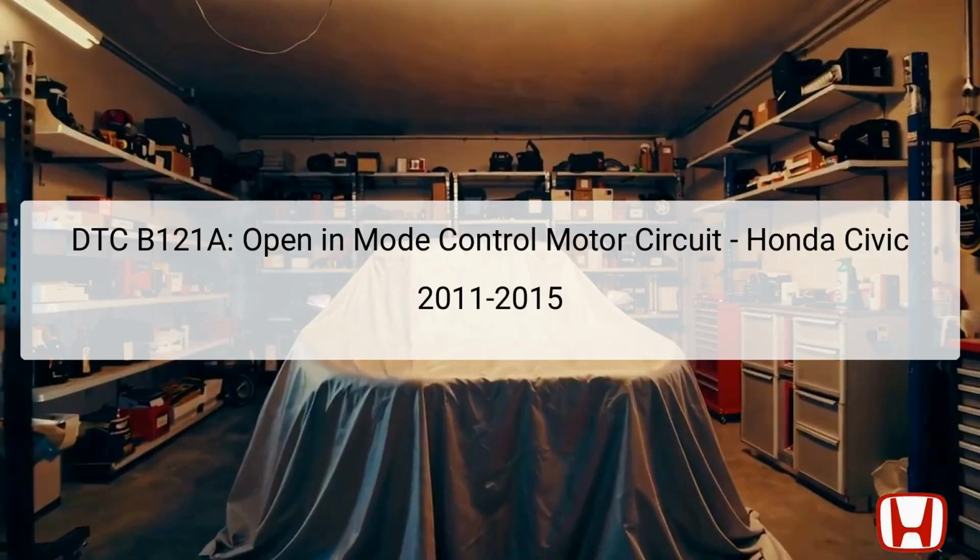This presentation covers the DTC B121A, also known as DTC Indicator 49, which indicates an open in the mode control motor circuit on the Honda Civic models from 2011 to 2015. This specific error highlights an issue with the mode control motor, which plays a critical role in regulating airflow direction in the vehicle's climate control system.